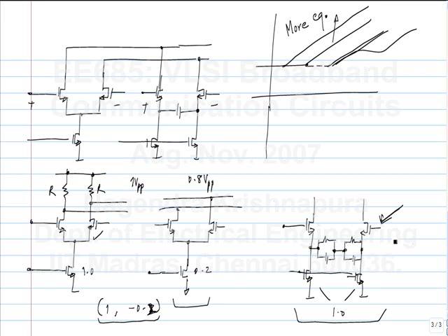It also has better control because you can digitally control the current and so. And the other thing is it will not suffer from the uncertainties of analog components. So analog components have a lot of tolerance, you know that. And the GM also has quite a bit of variation. So this R and C will vary quite a bit. So that means that the location of the 0 can vary quite a lot. Whereas with this case, the location of the 0, or effectively the response, is determined by the ratio of this current to this current, which is a very well defined quantity, okay, because of matching of components.